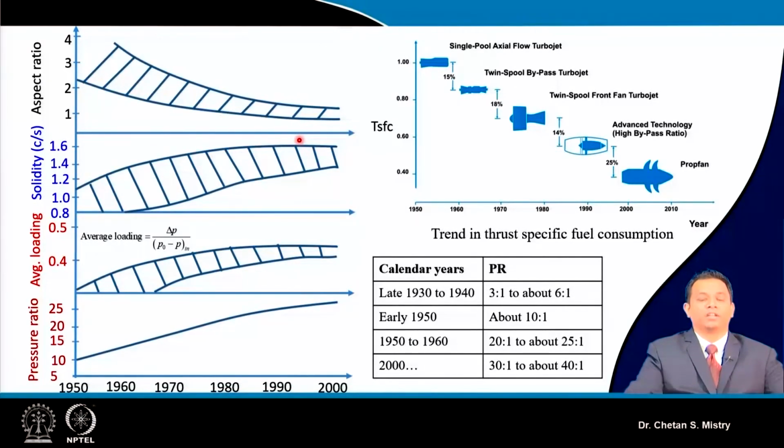Now, this shows what we have discussed today. This represents the global trend. In the 30s and 40s, the expected pressure ratio was low. As per requirements, especially for transport purposes, the pressure ratio has increased. Over the years it has reached almost 40:1, and for the most recent engine, the pressure ratio has reached 64:1. So over the years, our expected pressure rise has been increasing.